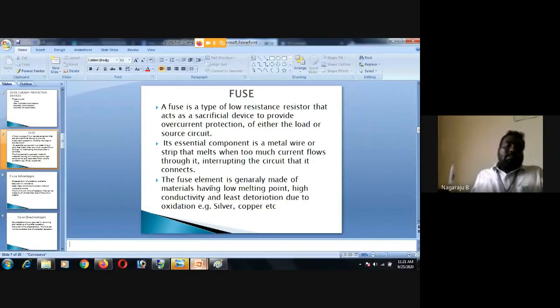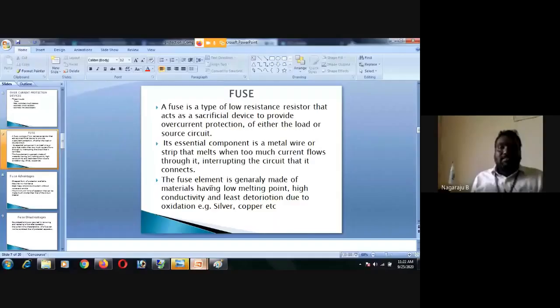So there is the ratio X by R at the point of application, as well as at the point of tapping. You need to know the X by R ratio. Depending on these things, fuse cutouts are selected.